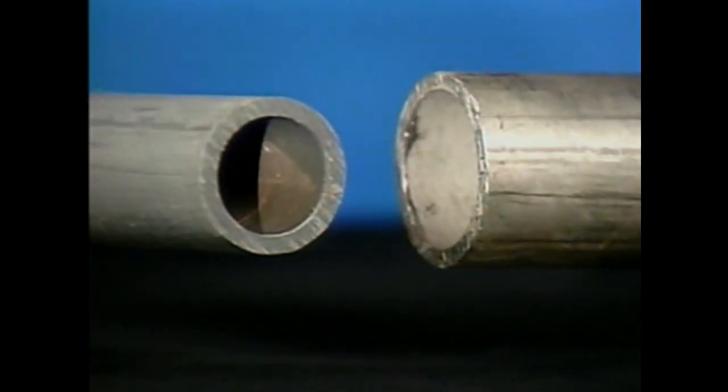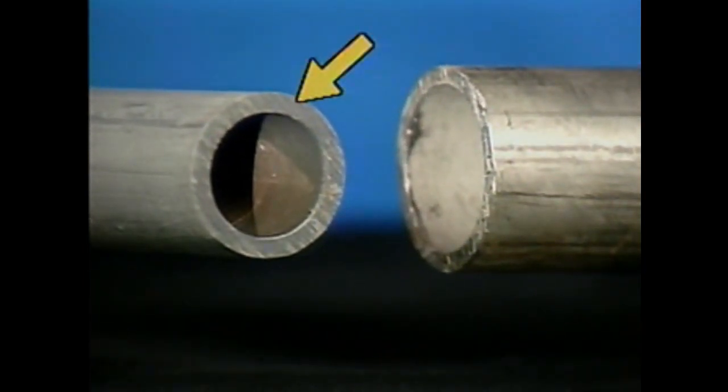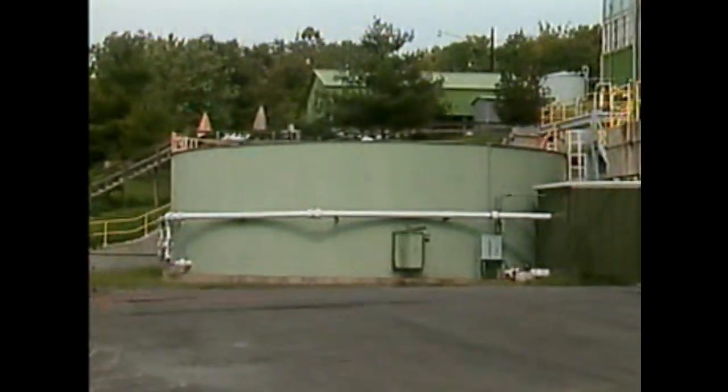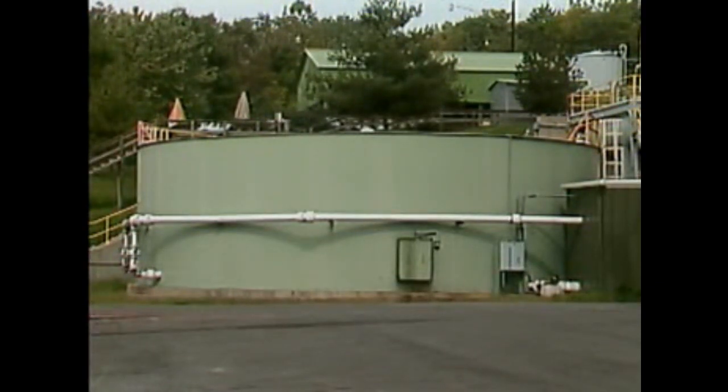Sometimes corrosion can be prevented by using materials such as plastic and stainless steel, which do not corrode under ordinary conditions. However, plastic may not be suitable for some high-pressure situations, and stainless steel may be too expensive to be practical. In some instances, tanks and other equipment are lined with materials such as plastic or cement, or corrosion inhibitors are applied to steel to minimize corrosion. These materials form a corrosion-resistant barrier between the water and the surface of the metal.